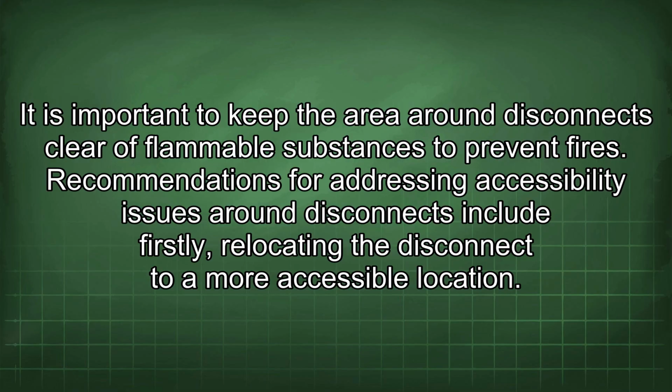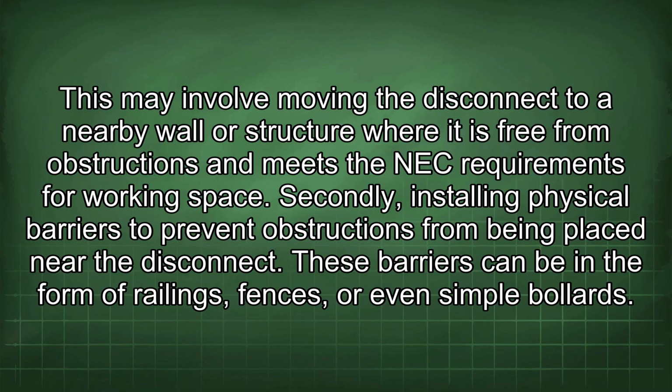Recommendations for addressing accessibility issues around disconnects include, firstly, relocating the disconnect to a more accessible location. This may involve moving the disconnect to a nearby wall or structure where it is free from obstructions and meets the NEC requirements for working space.